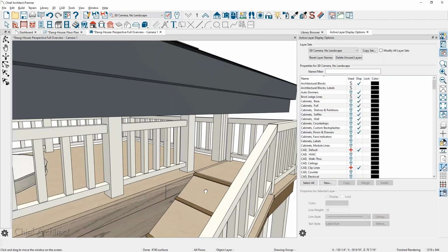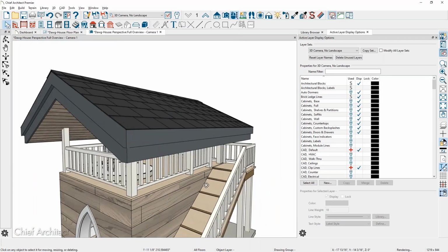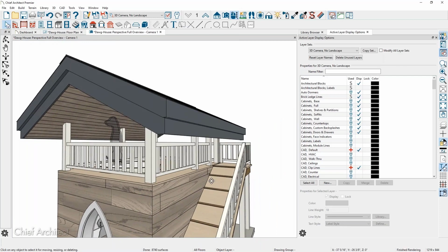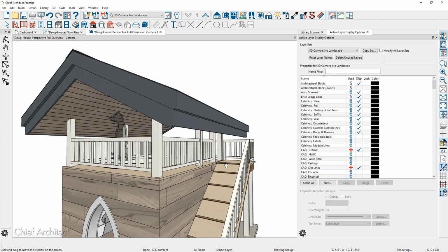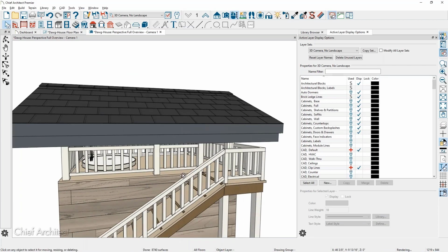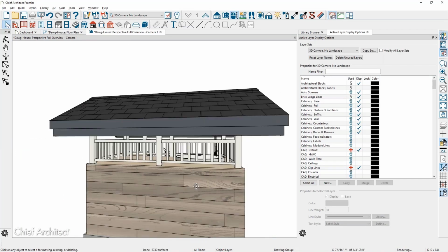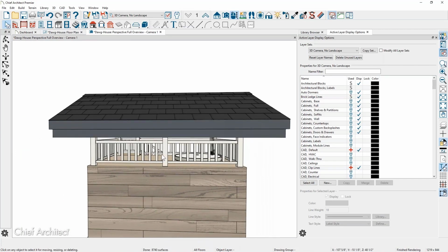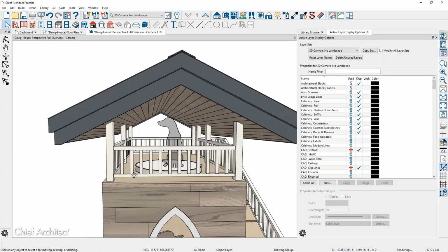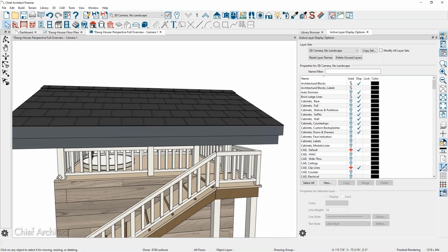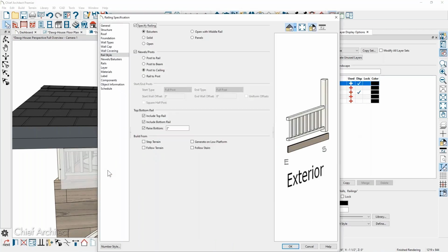Okay, thanks. We had Jenny write in. How did you line up the rail posts on the parallel wall to be aligned? That's a good question. If you look at the two parallel posts, we're talking about the one on the ramp side and then the one on the opposite side. And if you take an elevation view, this post right in the center should match up with the post on the ramp side.